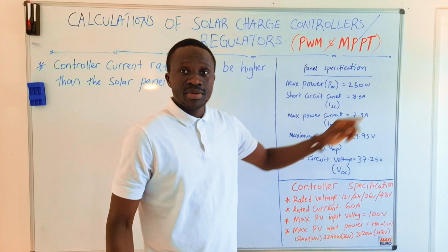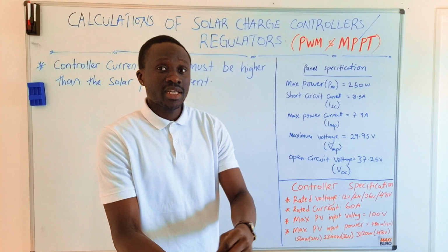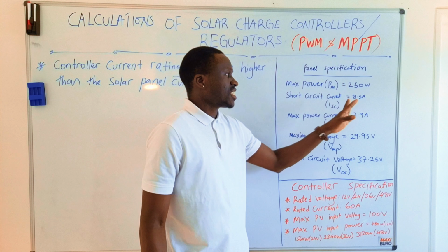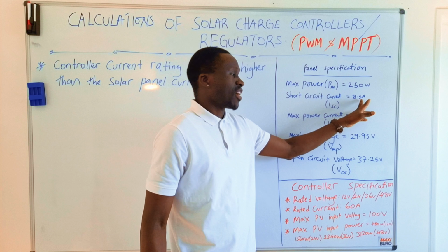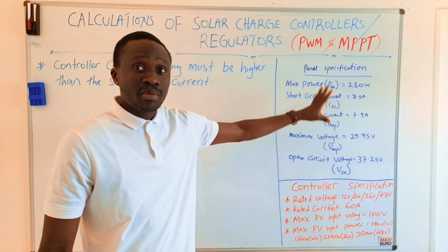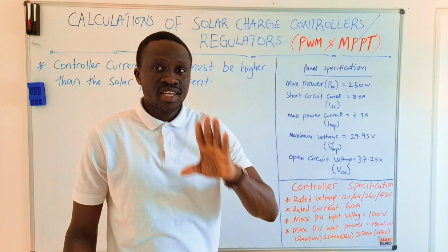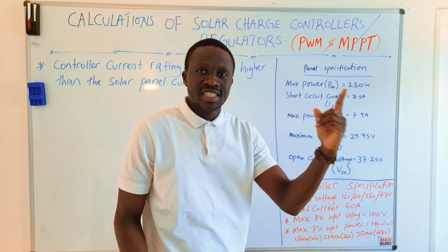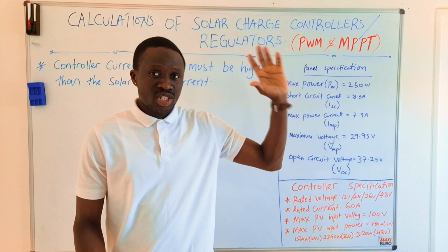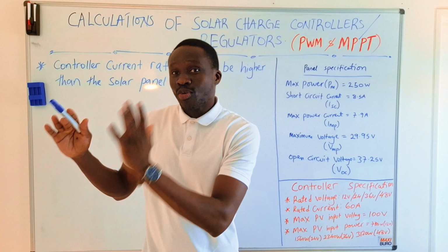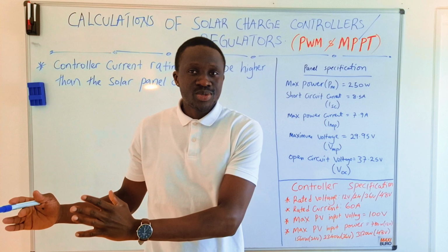This is the short circuit current when you have connected the panel to the loads. Let us say it is 8.5 amps, because we're going to use this information when you're calculating your regulator. That's why we first did the lectures about the solar panels, because without the solar panel you can't know which charge controller you're going to use.